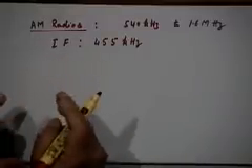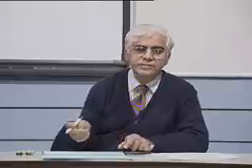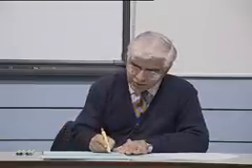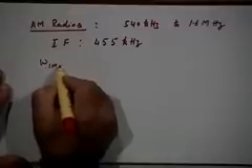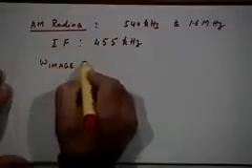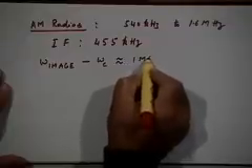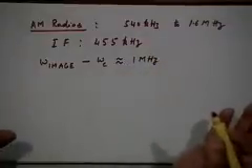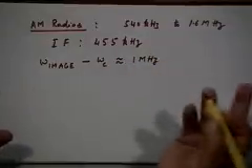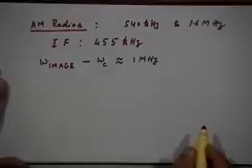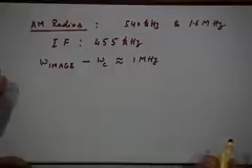So, what is the separation between any incoming signal frequency and its image frequency? 455 into 2, right. So, omega image minus omega c is of the order of 1 megahertz, almost 1 megahertz. 500 into 2 is 1 megahertz. What does it mean?